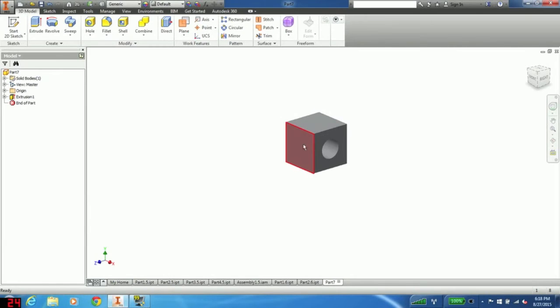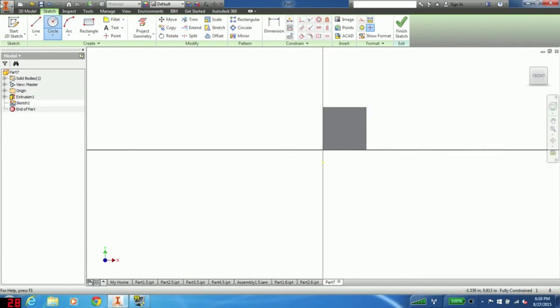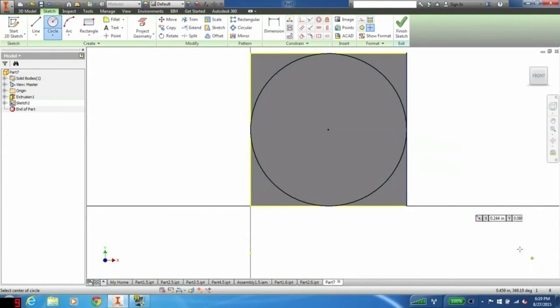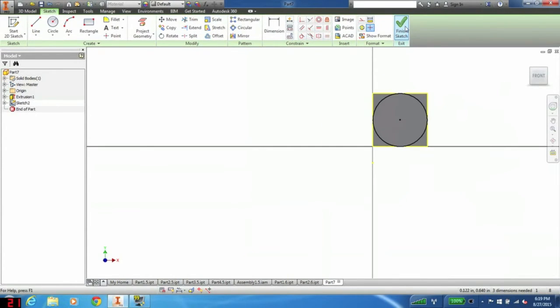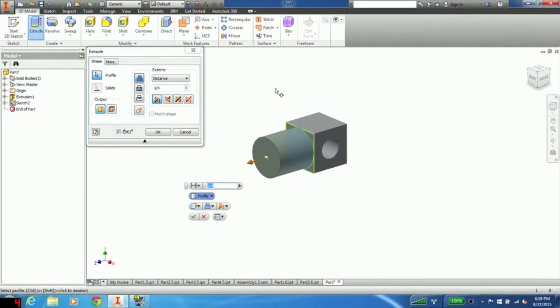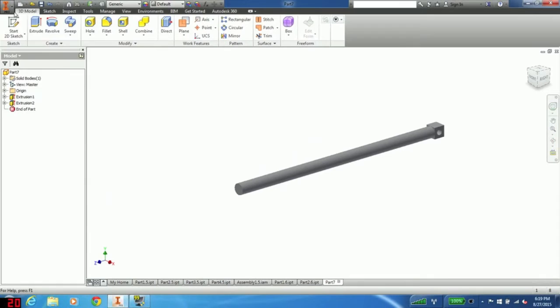And now we're coming off the side with this pin, so going to select the side by right-clicking, new sketch, and then we're going to use project geometry so that we can use those lines and line it up. And this time we're going all the way to the edge, so we can just move over to the edge until it locks to 1/4 of an inch. And okay, finish sketch. Then we're going to extrude this to 5 inches, just so it will extend past the shape no matter what. I'm going to save this again.